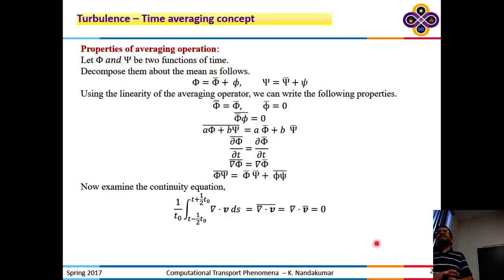And the theory, I guess, is if you take an LES model but continue to use a finer and finer grid, the results should approach that of DNS. Because the information that you lose in LES gets smaller and smaller as you refine. Otherwise, you are resolving everything else, right? So it provides a nice bridge from LES to the DNS approach, whereas the others are more ad hoc in that sense.